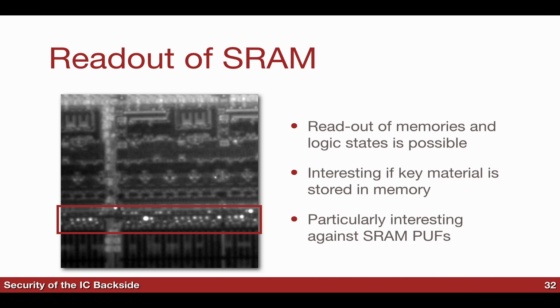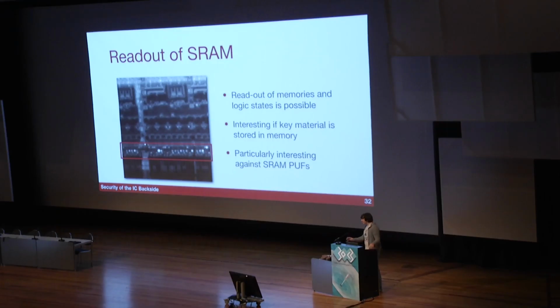But there are other things being proposed as well. If you get into hardware research in academia, one of the big things now is PUFs. A PUF is a physically unclonable function, and that means you figure out some way to have your device generate a unique response. The easiest way to do this is you take an SRAM, and each SRAM will have a different response. You power it up, and it won't just give you back either 1 or 0. It'll give you back some data.